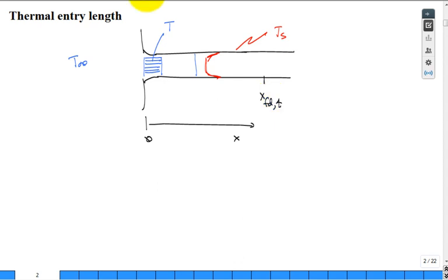Well, what does it look like at that length? Draw it here, and we'll sketch the walls a little further, and we'll put T_s and T_s, and it could be shaped like this if it's laminar flow. It won't be a perfect parabola, but it'll be close. What happens if it's turbulent flow down that length of the pipe? Well, then there'll be steeper gradients at the edges, and it'll be a flatter temperature profile in the core region, just like the velocity gradients were steeper at the wall and flat in the middle. We're trying to sketch temperature here.